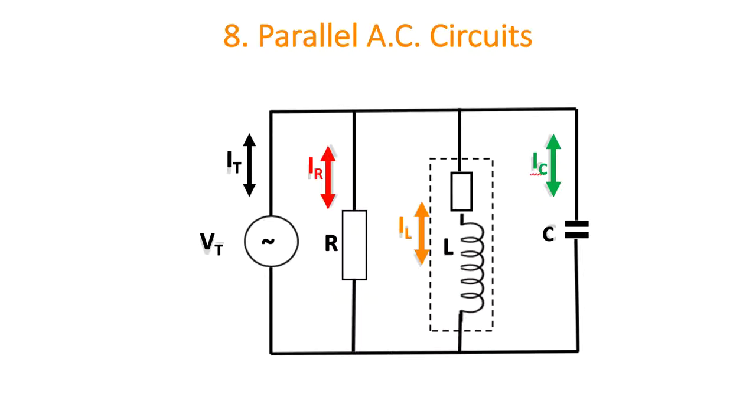So now we move on to parallel AC circuits. Similarly, I had students tell me I could just add up all the impedances. They remembered that they had to get the branch impedances. Then they thought, I'll just add up all the branch impedances and use that to work out the total current. Unfortunately, again, that's not true. Doing that does not allow for all the angles that the currents are at. Yes, we have to calculate the impedances to work out the currents, then put the currents in at the appropriate angles onto a phasor diagram, and then we can work out the I total.